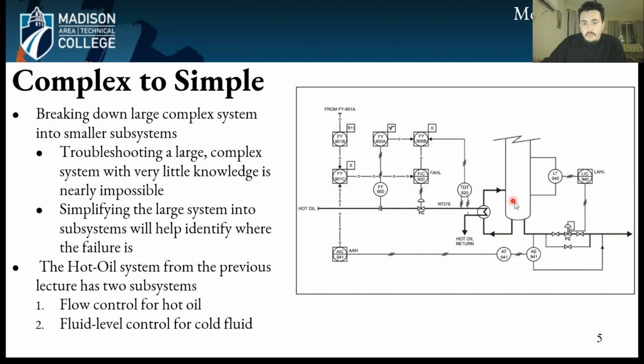And the cold liquid over here has a tank that has a level. And once the fill amount reaches a certain point, it turns this indicator, it turns this float switch or this transmitter on, and then we open the valve and let some fluid out of the bottom. So very similar to our feed water problem, and also we've looked at this before.